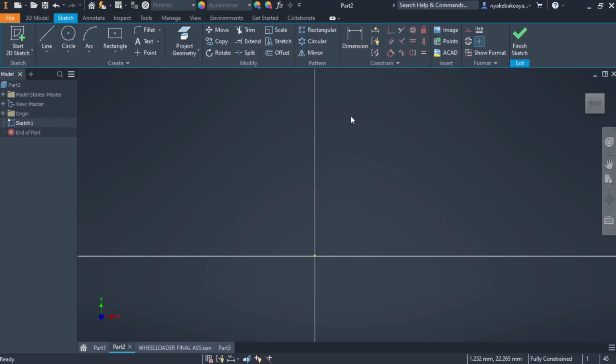A sketch is the basis, the foundation of anything. Once you have your foundation for the sketch, making anything else is very easy. This is what I mean. Let's say we were to make a square tube, and we want this side to be 20. You type 20, and then to put the other dimension, click tab, and then you can put 20 there.